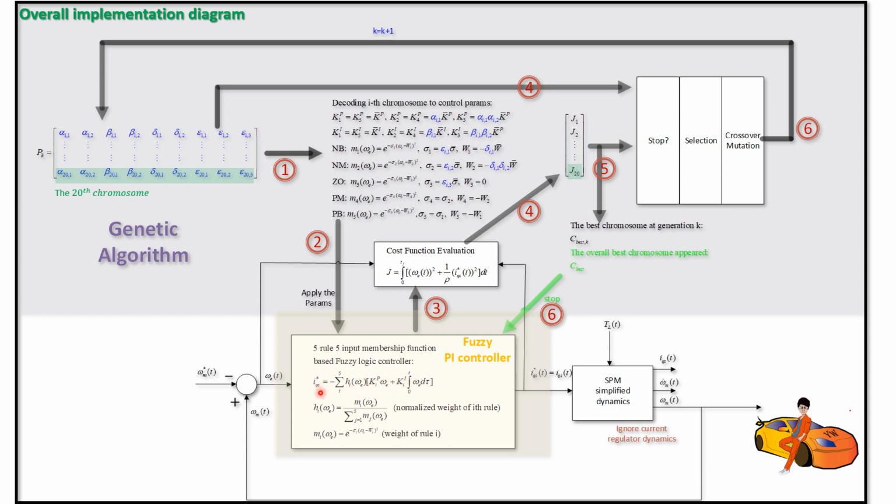It only provides the currents. Later on, I will show that there is an equivalent form that gives you the effective Kp and Ki. And that one is actually the one that I desired, because in most companies they are using PI controllers, and they want to know exactly how much Kp and Ki you actually tuned for the controller instead of just black box currents.